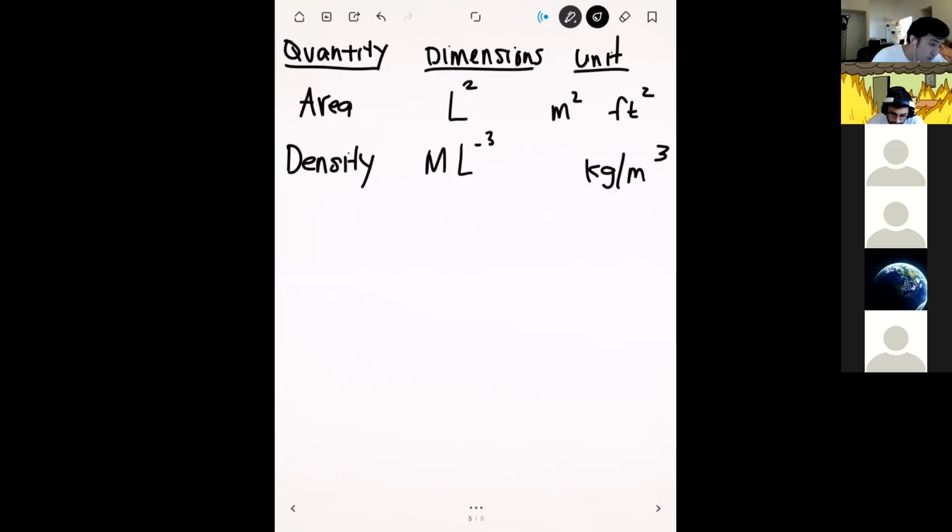Okay. Right. And so let's do pressure. Pressure is an important one, especially starting next week. Okay. So pressure, probably as everyone knows, is a force divided by an area. Okay. And so actually, what you can do sometimes, and you'll see this in the lecture notes, is that instead of mass, force is sometimes used as the dimension that covers that. So actually, pressure is more easily expressed in terms of force instead of mass. Right? So the dimensions would be F L to the minus 2.